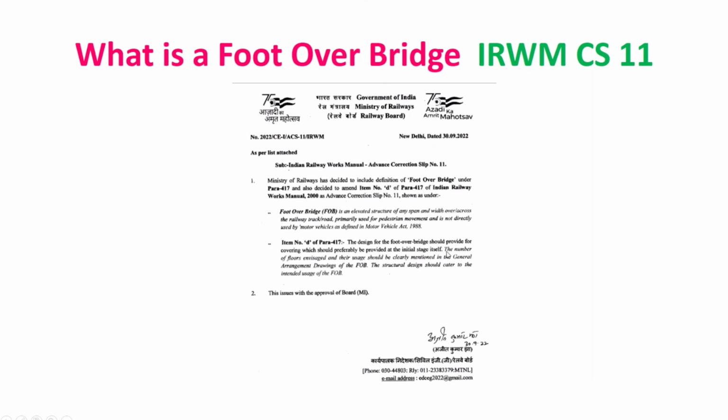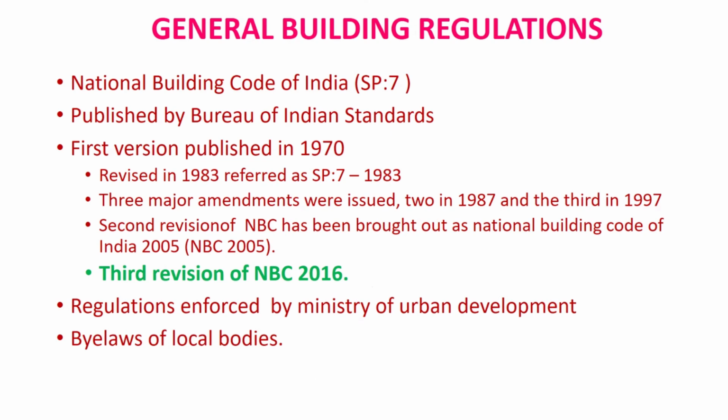Now here you can see the panel room. Suppose this panel has been installed. What they are saying is that the clear height above this particular panel for a panel room, 1200 millimeters, is the minimum requirement over this joist or the beam. Likewise, in case we have a DG room, a diesel generator room, it again specifies the height above the top of the DG set. Here it says that the maximum can go up to 3 meters.